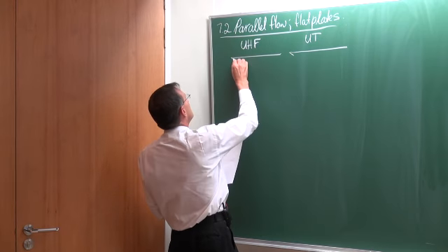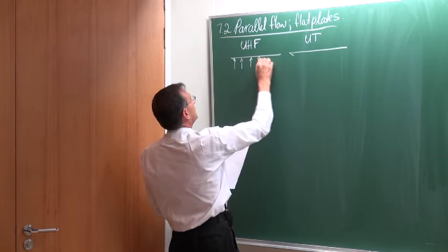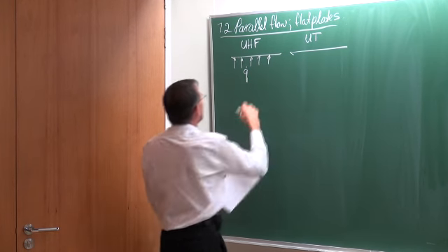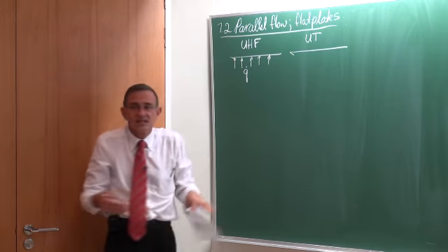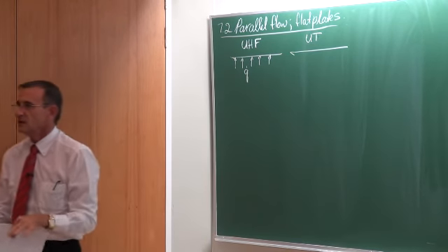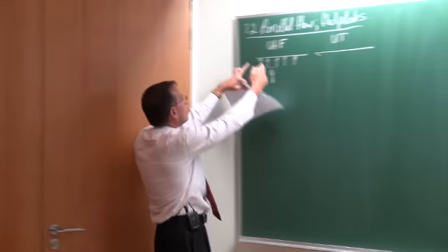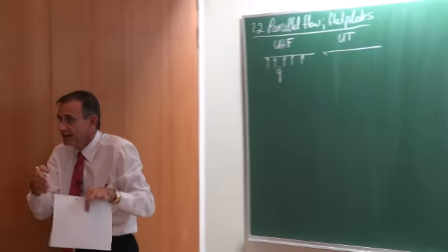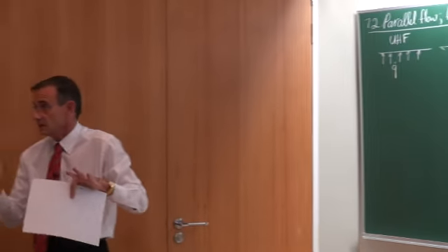With a uniform heat flux, it would mean that the plate would be heated everywhere. In every square meter there will be the same heat transfer. So if the heat flux is 1 kilowatt per square meter, then for every square meter 1 kilowatt of heat would go into the plate or the aeroplane wing or whatever the body is, it doesn't matter.